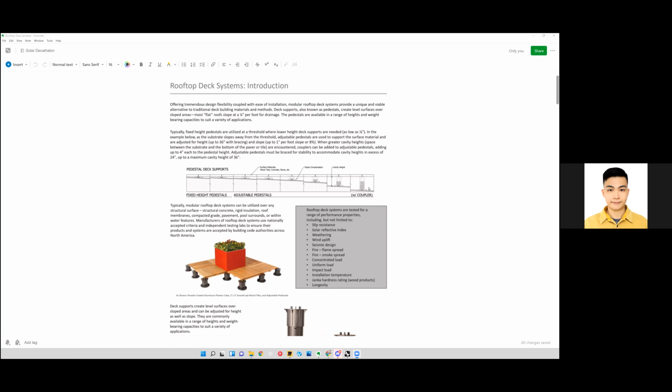I think the footing system is totally fine, but the only decision we really have to make is what to put on top of those footings. Yeah, there are essentially 2 general strategies. One is tiles, where you just have tiles and they only span between these pedestals, or you have systems where you put joists on top and then you can use larger sections of boards. So it probably just comes down to whichever one's cost effective. The tiles have a lot of flexibility in material types, which is nice. So you can do different zones with different types of tiles.